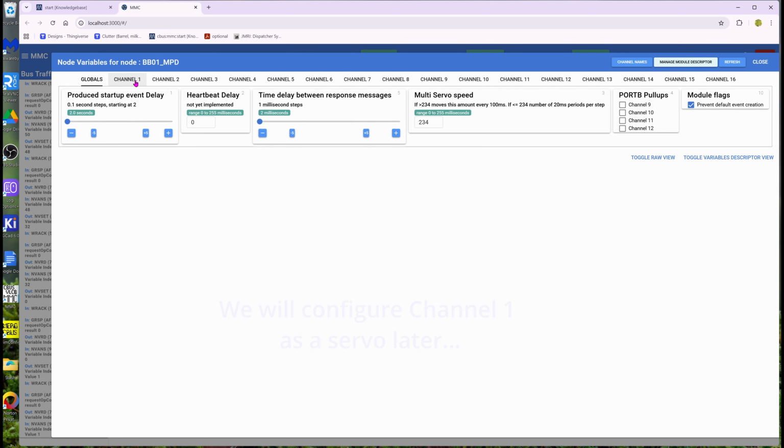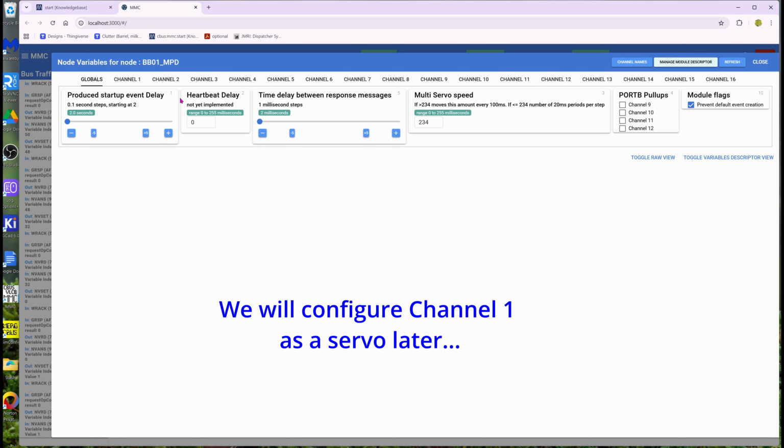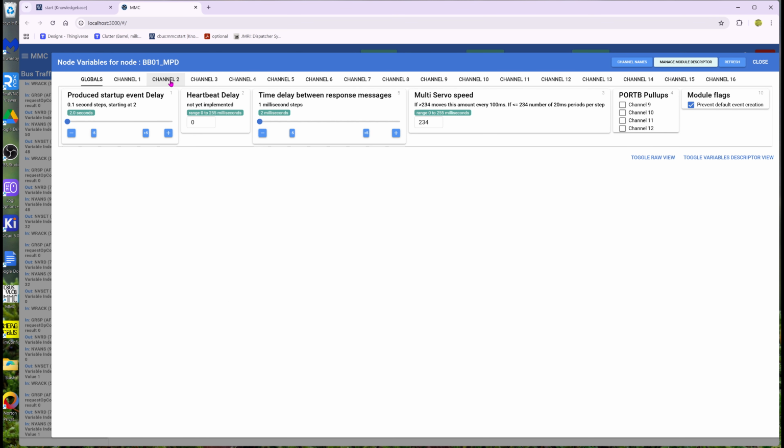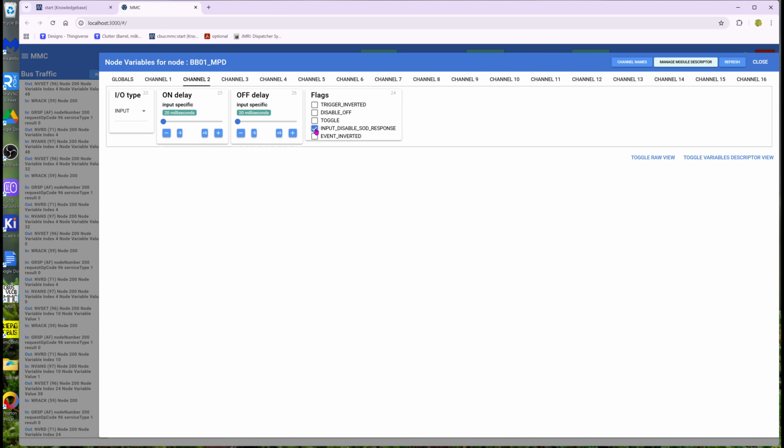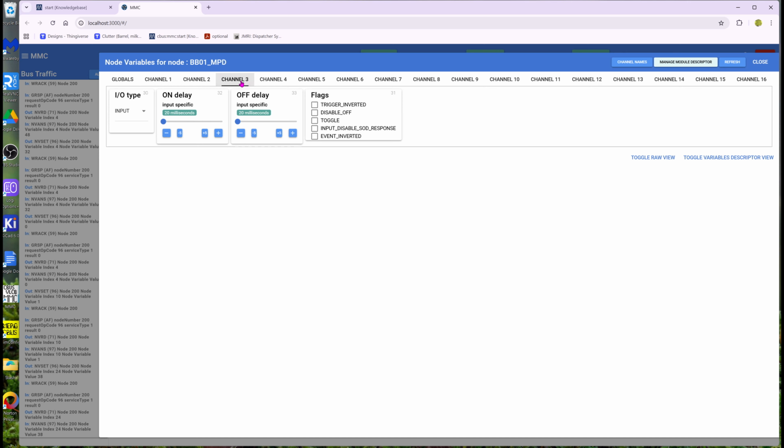I know I'm going to use channels 1 and 9, but I know I'm also getting feedback for all these other channels. That's a bit silly. I can do one of a couple of things. Channel 2, I could change it to be an output, and then it's not a feedback style event. It's not a produced event. I won't get start of day information. Or I just come in here and I turn off start of day responses for these other channels.